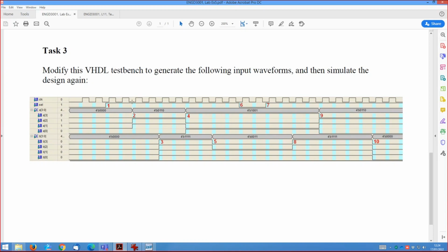If we look at a relative plus 5 nanoseconds to sel, change number 2 is a change in A from 4 zeros to 0110. Then again, we want to wait 2 more rising and 1 falling plus 5 nanoseconds, and that will take us to change number 3, which is to change B from 0000 to all ones.